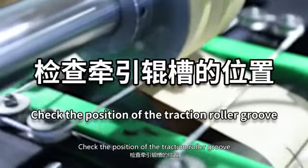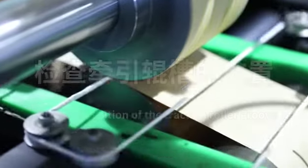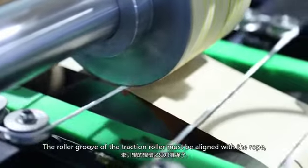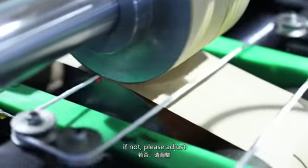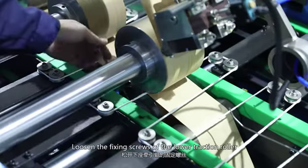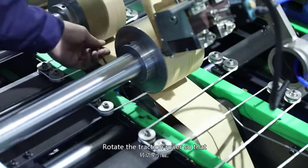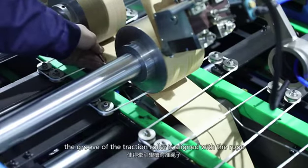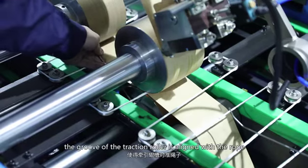Check the position of the traction roller groove. The roller groove of the traction roller must be aligned with the rope. If not, please adjust. Loosen the fixing screws of the lower traction roller. Rotate the traction roller so that the groove of the traction roller is aligned with the rope.